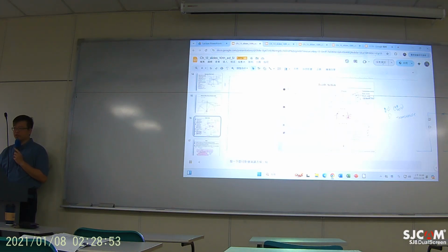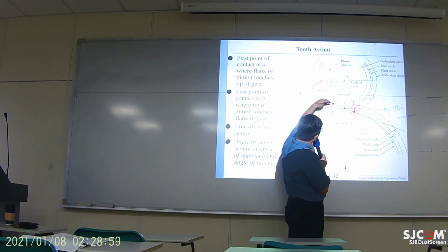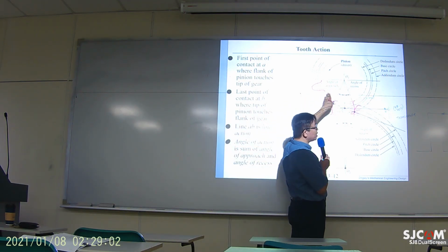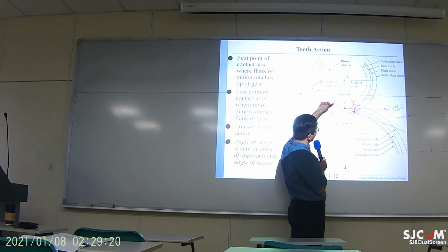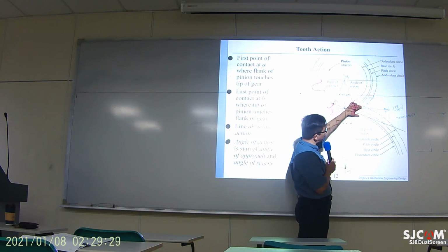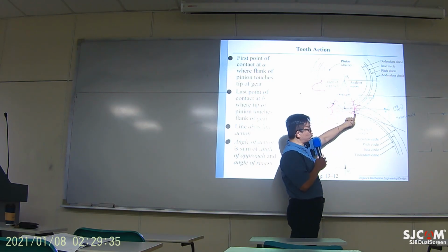From this particular drawing, you can see that when your mating teeth are shown in this configuration, if you are standing on the bottom side of the gear, the force is applied at the tip of the tooth, but when the gear rotates to this particular position, you can see that the force is pushing the root of the tooth.